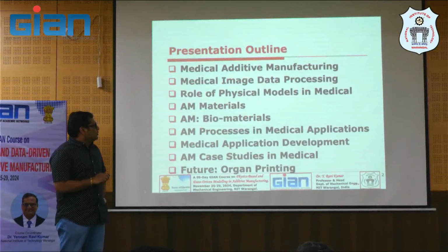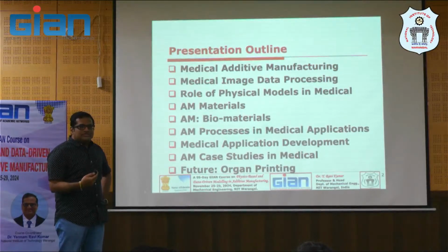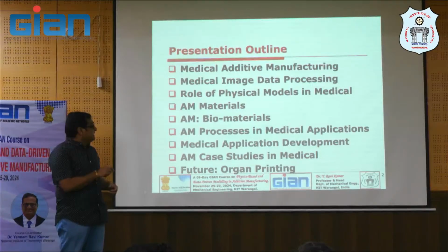So then we are going to use medical image processing for that. And once you have done the medical image processing of the images, we can save it there itself as an STL file. So basically we need an STL file to 3D print, or to additively manufacture, your model. In this case it is a biomodel, which has been acquired from the patient data.